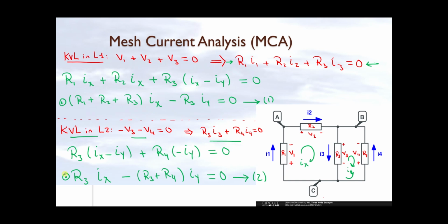So in conclusion, in this video we reviewed 2 basic circuit laws, KCL and KVL, but KCL and KVL alone are not sufficient because I may have a number of equations less than the number of unknowns. And here comes the trick in the node voltage analysis and the mesh current analysis. The trick is, if you write a KCL, you replace the current as a voltage over a resistor, and then this voltage of an element can be represented as a difference between the voltages of the two nodes connected to that element.